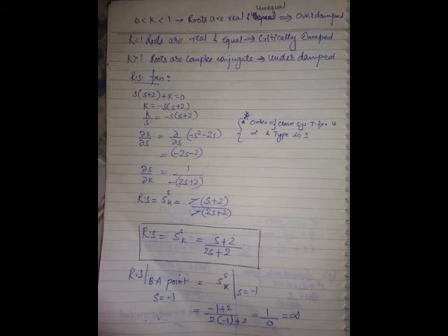This is the three-term controller equation given. So Laplace transform of this will become 20 into 1 plus 1 by TiS plus TdS into E of S. You should not consider these integral limits, because all initial conditions we assume to be 0.